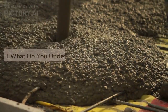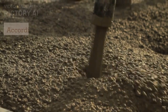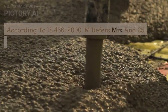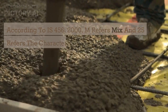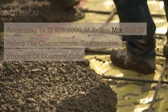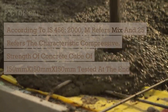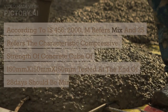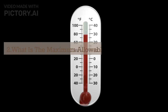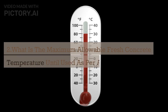1. What do you understand by M25 concrete? According to IS 456-2000, M refers to mix and 25 refers to the characteristic compressive strength of a concrete cube of 150 mm x 150 mm x 150 mm tested at the end of 28 days, which should be a minimum of 25 N per square millimeter. 2. What is the maximum allowable fresh concrete temperature until used as per ASTM?